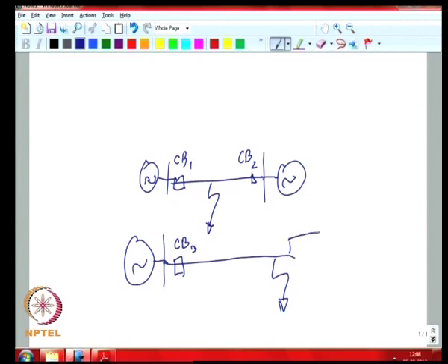So, if you now connect say a distributed generation source over here, then you have this issue that now to clear a fault that you had on the DG system, you have the issue that you had in this previous case, where if you just open this breaker, there is now the potential that this DG source would actually feed the fault, and then you have now the issue of being able to coordinate multiple DG sources, not just one potential source. Every customer on that feeder might potentially connect DG, and you need to make sure that those sources get disconnected when the protection philosophy of the feeder has to actually kick in.